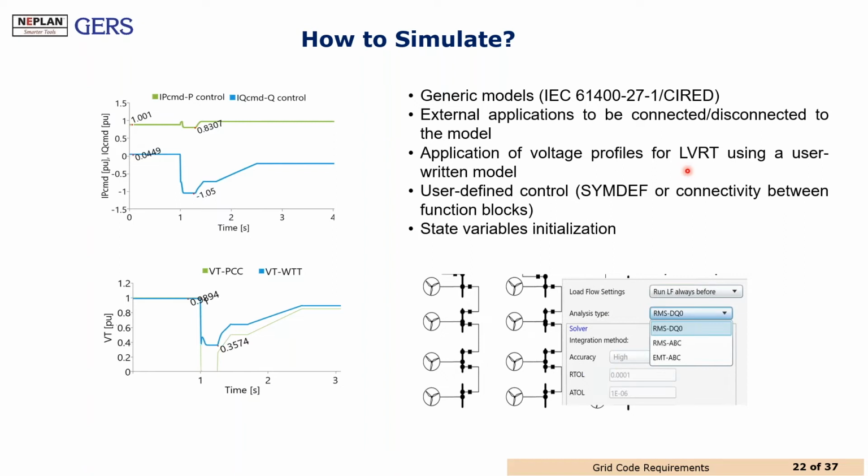If the generic model is not acceptable, we have to create a user-defined control. SYNDEF is the language that NEPLAN is able to support to create this kind of user-defined models, or using function blocks to connect the transfer functions. Finally, the variables initialization, and this is very important to take into account these requirements, because